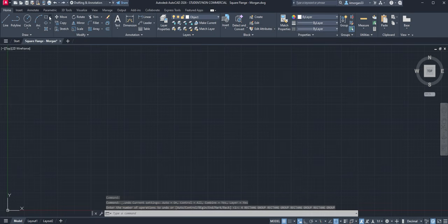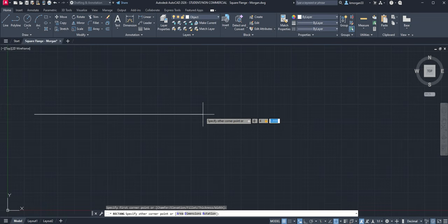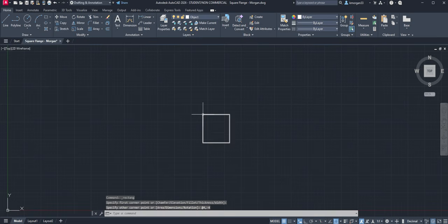So right now let's escape it, go back, and start with a rectangle. It's asking you to specify the first corner point. So we move this cursor approximately to the middle of your drawing area. You can click on it and then start typing. I'm going to show you how you can make some mistakes. Don't click on the period instead of the comma. Comma means we go to the next box right there, where you can input -4 and then enter it.